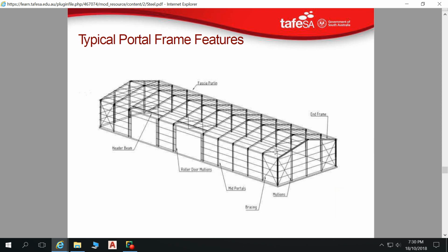But if not, here we can see they've put bracing in over top of these openings as well to assist that, because if there's going to be a weakness in this structure, it's going to be where we've got an opening. So bracing in the corners, bracing in the end panels, and then bracing above openings. And then any more bracing you need spread out equally throughout the frame.